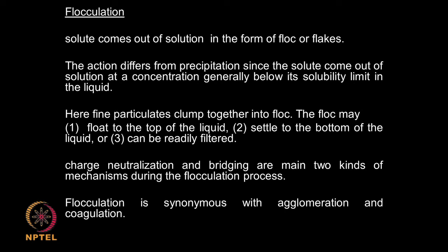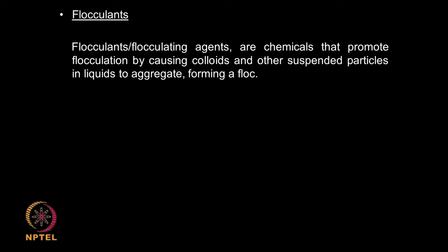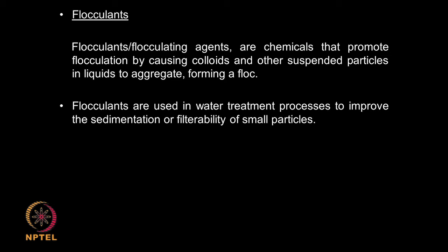Okay. So, instead of flocculation we can also call it agglomeration, we can also call it coagulation. So, you add a coagulating agent, or you add a flocculating agent, you add an agglomerating agent. So, they are all synonymous to each other actually. Okay. So, there are a lot of flocculants that are used, synthetic chemicals, natural chemicals and so on, that are generally used to break this type of charges. They are generally used quite a lot in water treatment plants, they are used in environmental plants when you are remediating the effluent that is getting discharged and so on actually.